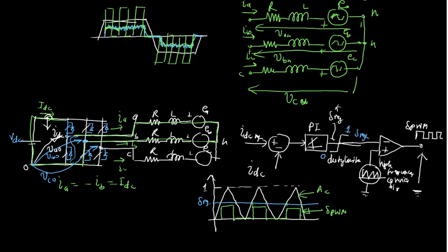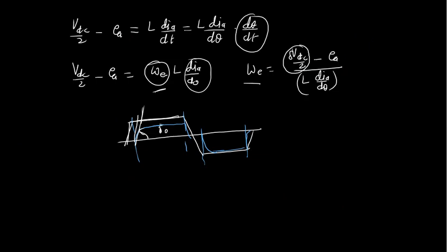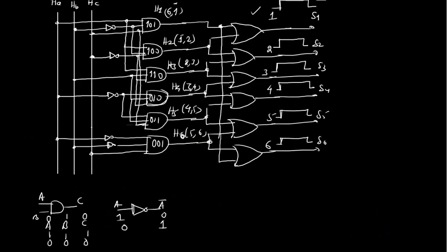Now you see that you have this delta PWM generated. Please go back to where we left our Hall sensors. So this is the situation. The Hall sensors' switches were selected. If you give it like this, what will happen? The switches will be unmodulated. You will not be able to run your vehicle with a variable speed. So what we have to do now is make the variable speed. How can we make it? Because we have a zero current control, if you change the torque, the speed will be changed.